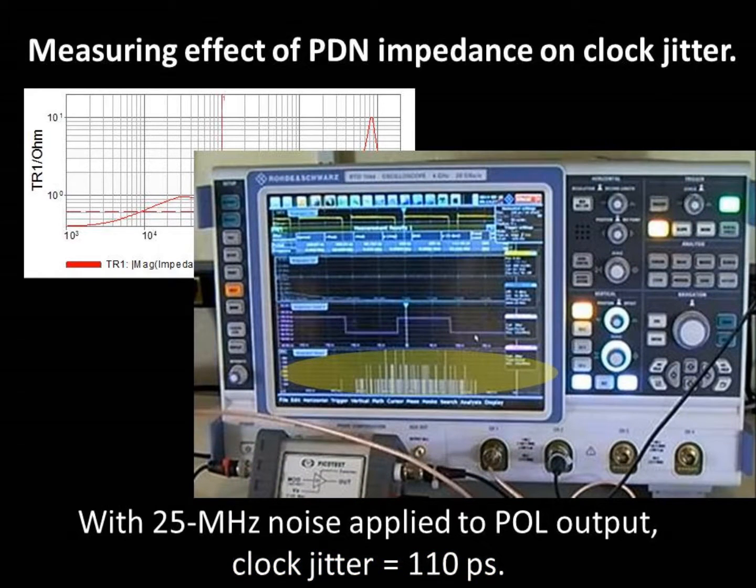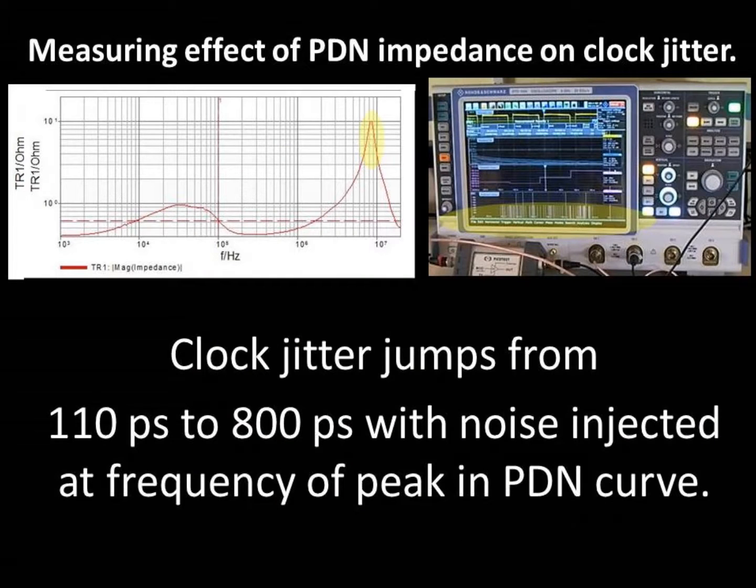And then if we continue to increase the frequency of the modulation on the power supply to 25 MHz, the jitter measurement returns to 110 picoseconds. So this experiment demonstrates one impact of a peak in the PDN impedance curve, a degradation in clock performance.